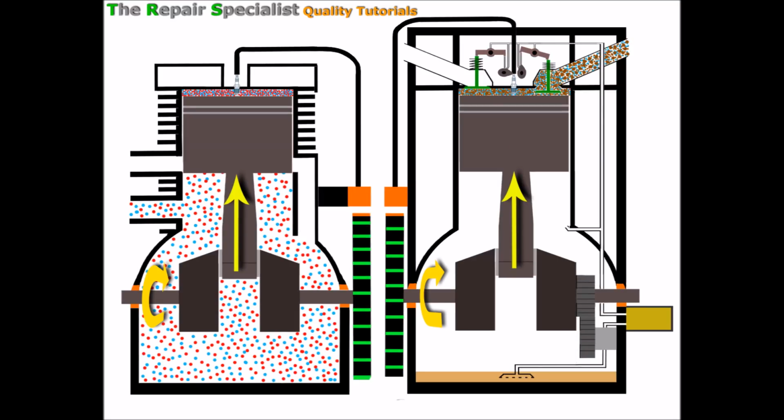Going on from here and allowing the pistons to rise again, we know what's going on now. On the 2-stroke we've got full compression because we're at top dead centre, and it's the same in the 4-stroke, where all the exhaust gases have been pushed out through the manifold and there's only a small amount left. At that point, we know our magnets align up with or just past the coil packs, creating electricity up through the HT leads to a spark once again.